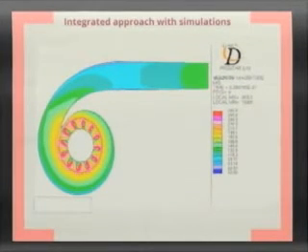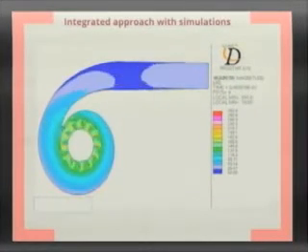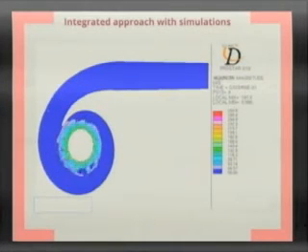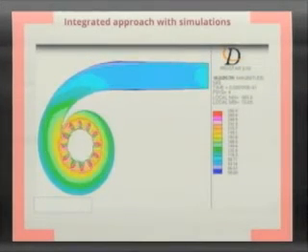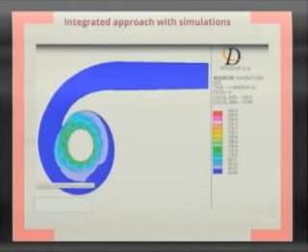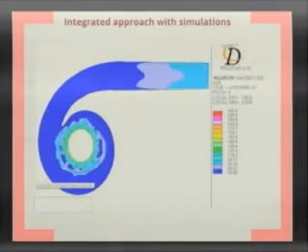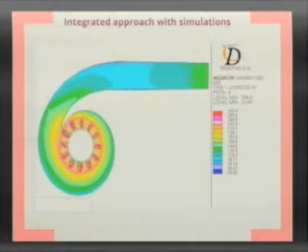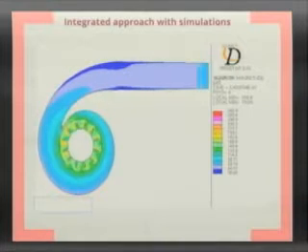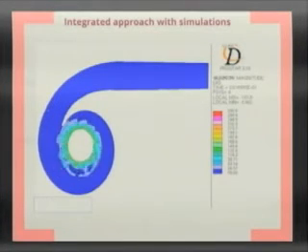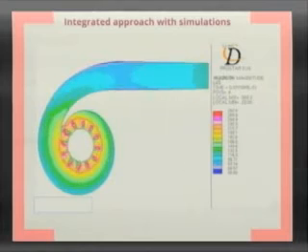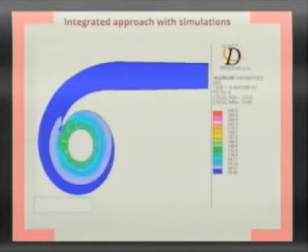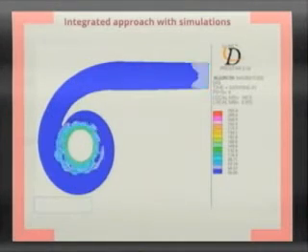If we look at a simulation, this was in 2005. This is the first simulation ever conducted on a full stage by one of my students, Dean Palferman, and he simulated with CFD a full stage in full rotation. This is velocity magnitude. You see changes in color indicating velocity changes from 50 meters per second in blue to 282 meters per second, which is a great deal, in red. And the whole flow field is fluctuating and changing.